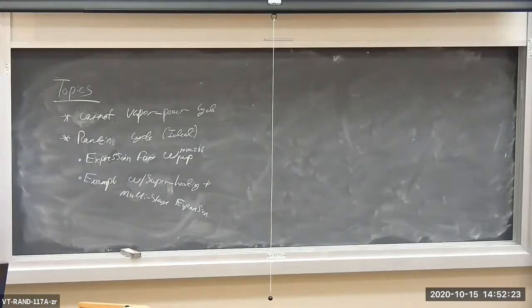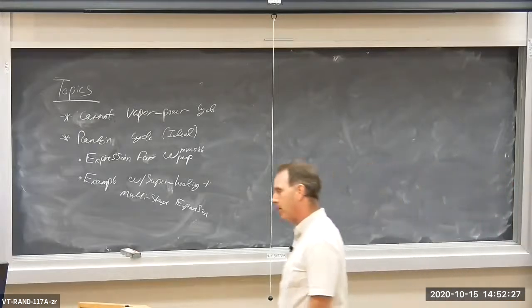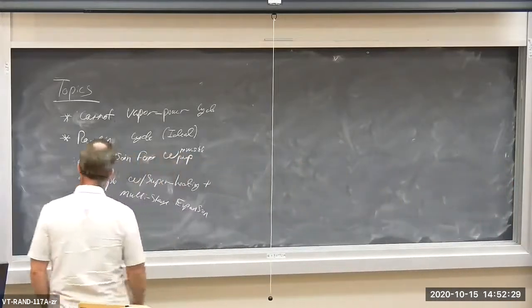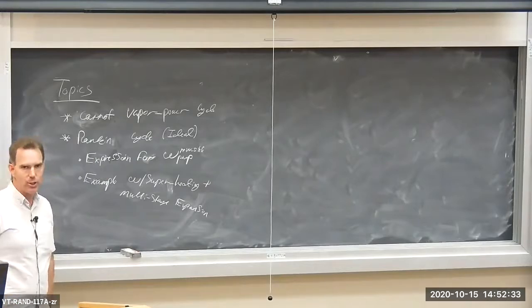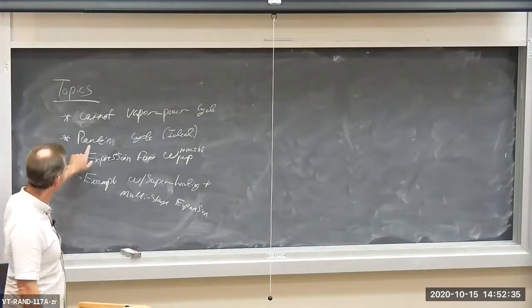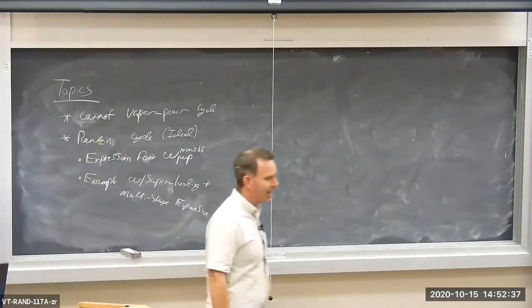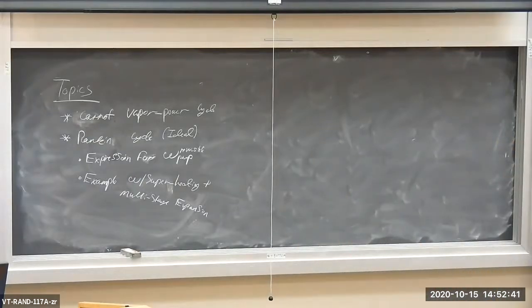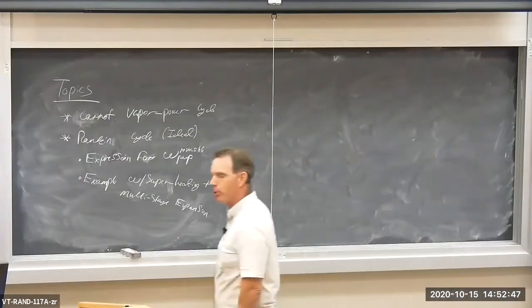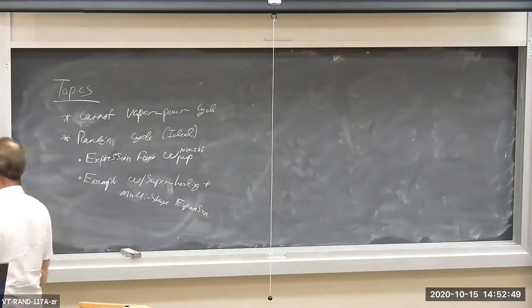Then we're going to modify the Carnot cycle, make it a bit more technically plausible, technically feasible. And the result will be a Rankine cycle. R-A-N-K-I-N-E, Rankine cycle. So we're going to take a Carnot cycle, which is operating inside the saturation dome, and we're going to produce the Rankine cycle after we modify it.